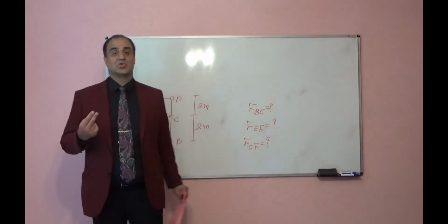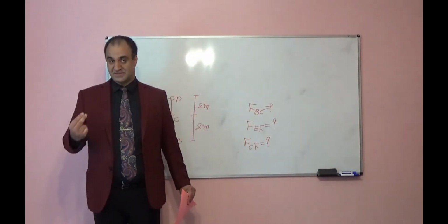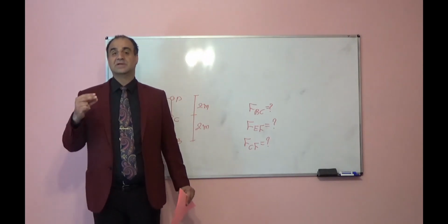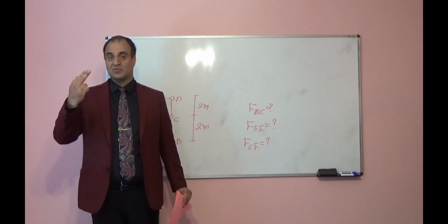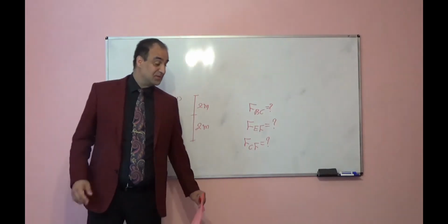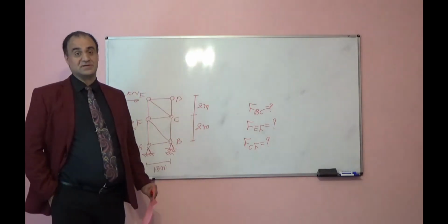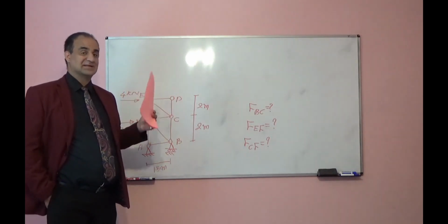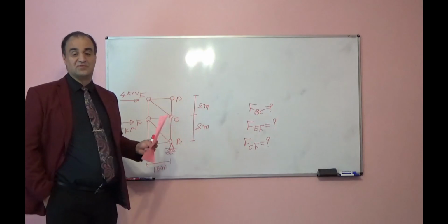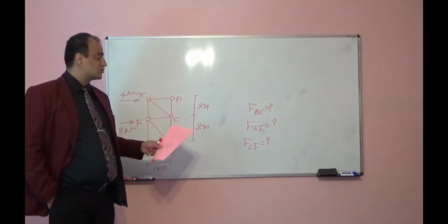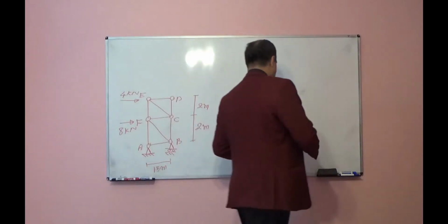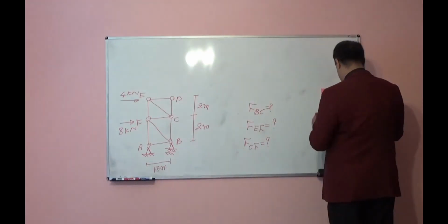One of them is joint method. You will first find reactions and then you will cut joint by joint, and you will start from that joint. We have only two members, two unknowns. Find zero force member. Use those tricks I explained last session and find zero force member. And then solve using section method and compare your answers. So this is one problem.